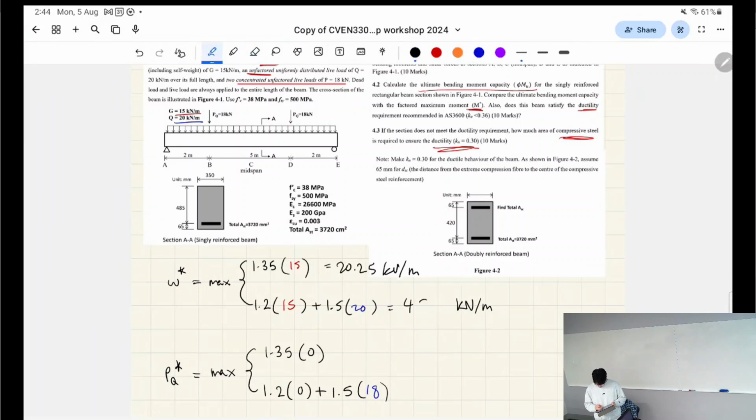Okay. Basically, let's explain how these point loads work. If we have the case of dead load governing, so for example, if it was actually 48 somehow, then we'd have to use these two combinations of loads together, meaning there wouldn't be any point loads for the case of purely dead loads.